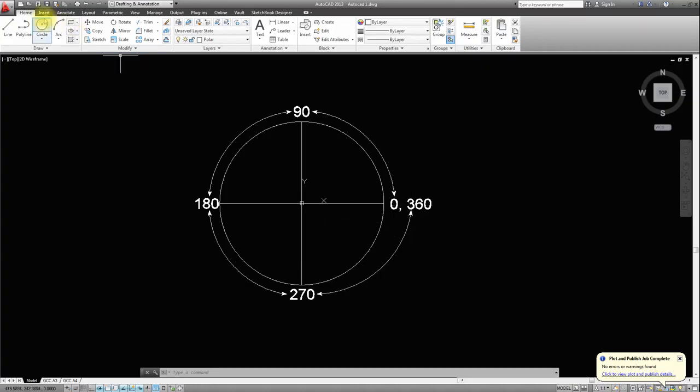So if you drew a line that was just below this one here, you can see the angle will come up. It's saying 2 degrees. If you type 2 degrees into AutoCAD, it will go into the first quadrant. In this bottom quadrant here, your angle will be between 270 to 360. If you want to draw a line in that segment, you would have to give its angle. See that one there, it's saying it's 3 degrees, but it's 3 degrees below 360.